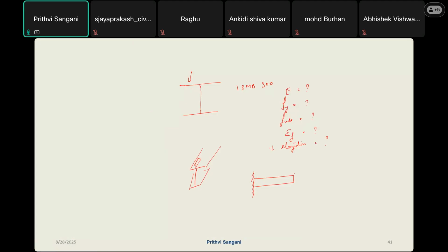You will clamp it here and you can clamp it over here. But there is a problem with this kind of arrangement. When you're testing a strip, you will exert a tensile force and see what the stress and strain are in between this section. But remember stress concentrations, the Saint Venant's principle. It says that wherever you have the forces acting, there you have a higher concentration. So at these places you have a higher stress concentration.